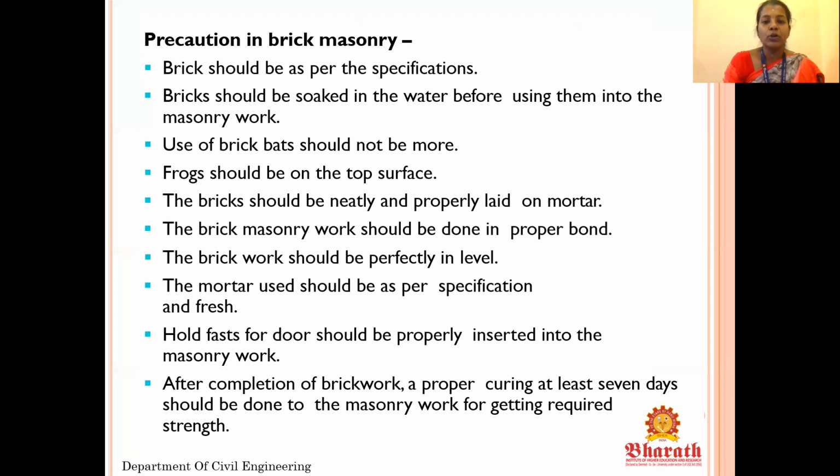The brick masonry work should be done in proper bond. The brickwork should be perfectly in level. The mortar used should be as per specification and fresh. Hollow doors and window frames should be properly inserted into the masonry work. After completion of brickwork, proper curing for at least 7 days should be done to the masonry work for getting required strength. So these are the certain precautions